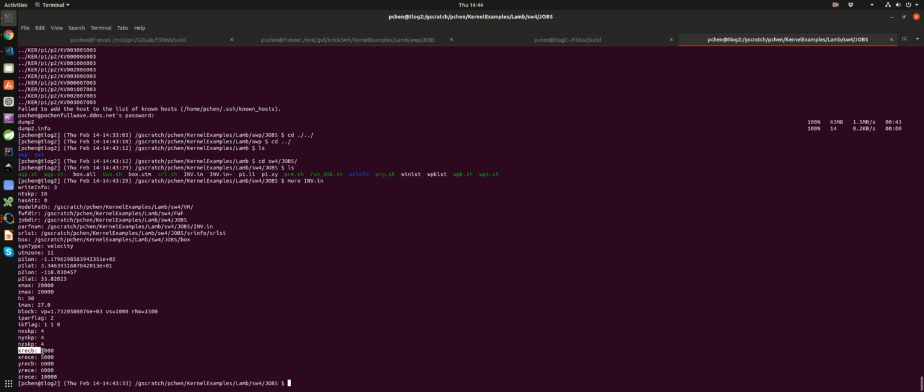One is that for SW4, I can specify the x and y starting and ending region for storing the kernel, or for storing the strain fields. So XREC-B is 5 kilometers, and XREC-E is 5 kilometers. So in the x direction, I start to save the strain fields from 5 kilometers to 5 kilometers before the end of the x direction, and then in the y direction I'm starting to save at 6 kilometers,